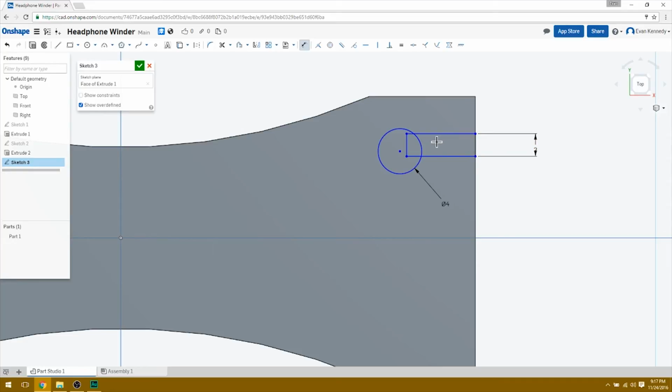The next thing that I'm going to do is I want these to be centered. The way I can do that is by setting the distance from the center point of my circle to one of the edges of my rectangle to half of whatever the height of this was. So you can just enter 1, obviously that's half of 2, we're not silly. But if that's a really complicated number, what you can actually do here is input equations.